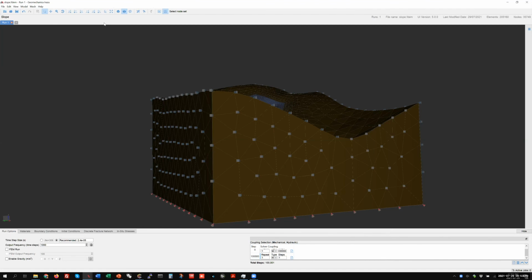Another question that's come in for Irazu is, is it possible to model rock structure support interaction in Irazu? I assume by support you mean support elements like rock bolts. If so, yes, you explicitly incorporate support elements the same way as you explicitly incorporate discontinuities. So that could be modeled explicitly as well.